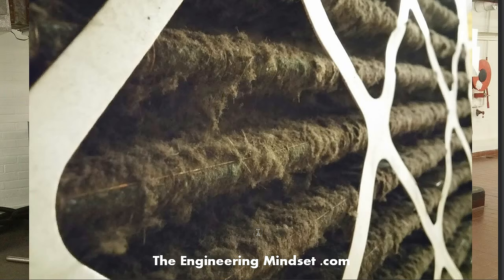So this is just pollen, this is bits of skin, this is dirt, this is where cars drive along the roads and they give off all the CO2, and their tires degrade and all that rubber comes off. This is all coming in, this is all collected on here. So this is why it's important that you have filters on your airstreams, and that you clean these regularly, just to make sure that that is not entering your building, well, into your equipment, and also that the occupants inside are not breathing this in.